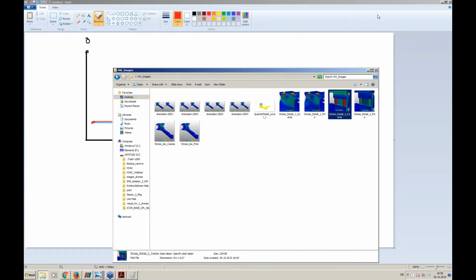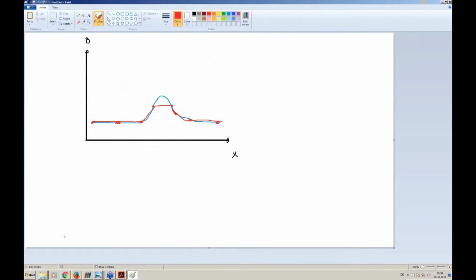And there's already a first question by Awad. He wants to know how can we find out about this mesh independency. And for sure, experience is very important. But if you have no idea, start with, as I mentioned, a coarser mesh and refine it more and more. Okay, yes, that was our small retrospective on the homework.